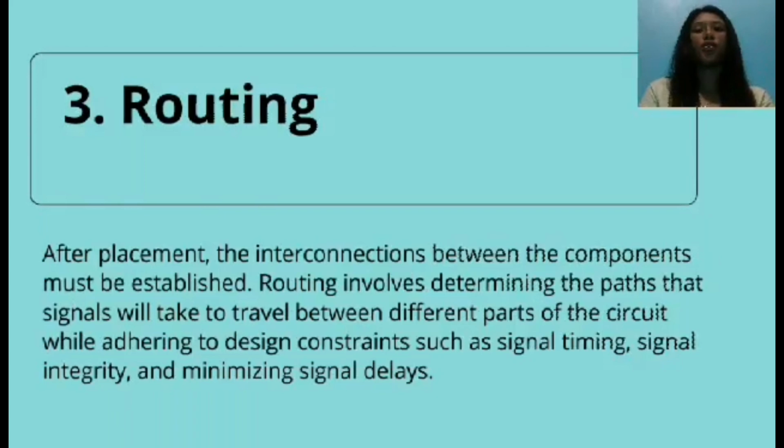Next is routing. After the placement, the interconnection between the components must be established. Routing involves determining the paths that signals will take to travel between different parts of the circuit while adhering to design constraints such as signal timing, signal integrity, and minimizing signal delays.